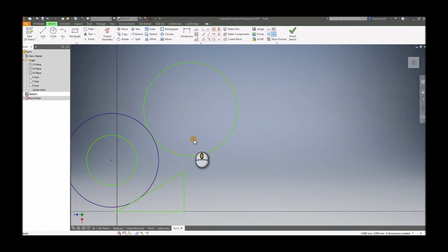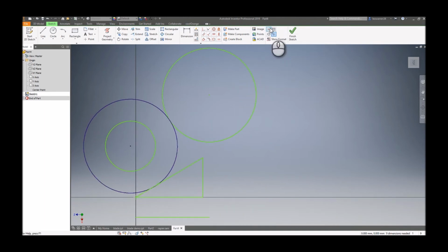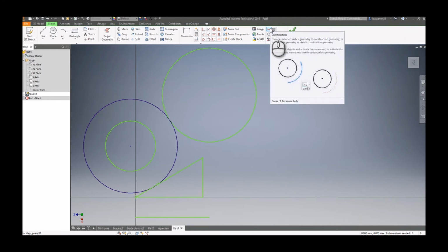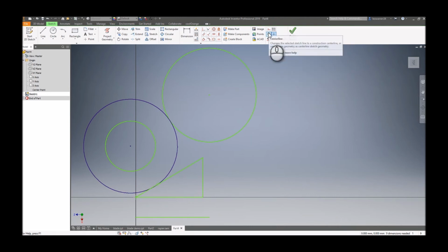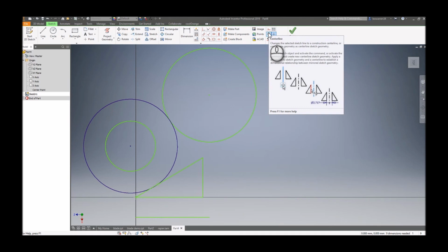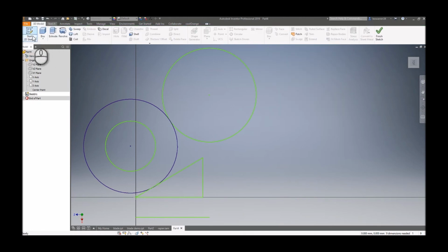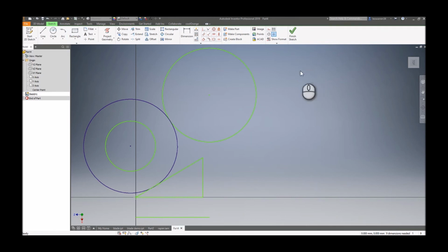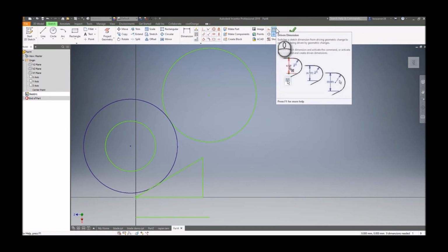And finally, last but not least, you've also got the actual sketch types. So this is called a construction sketch, so it doesn't actually interfere with extrusions when you try to 3D model, but it's useful for when you base constraints around them. Then there's centerline, which is better for revolves, coils, certain sweeps, because it'll automatically detect that it's a centerline and start trying to rotate around it, so it's kind of like an axis. This one is a driven dimension, so this one actually dictates to the other dimensions, I'm the boss.